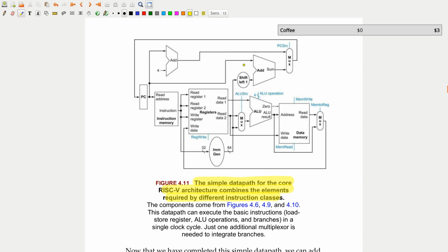So we have this additional immediate value generation hooked up also to calculate the branch target, and we can select whether or not we're going to be using just the next program counter value or we're going to be using the target value. We see we have the same mem to reg and ALU source controls that determine whether or not we're doing a memory or we're doing an R-type or arithmetic instruction.